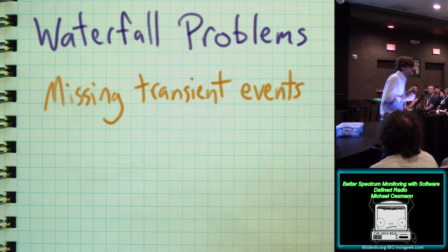But there were 20 million measurements made in that second. You're only seeing 100,000 out of 20 million. And in most cases, that's probably the best case scenario. Roughly speaking, you're probably missing hundreds to maybe 1,000 times the information compared to what you're actually seeing on screen.